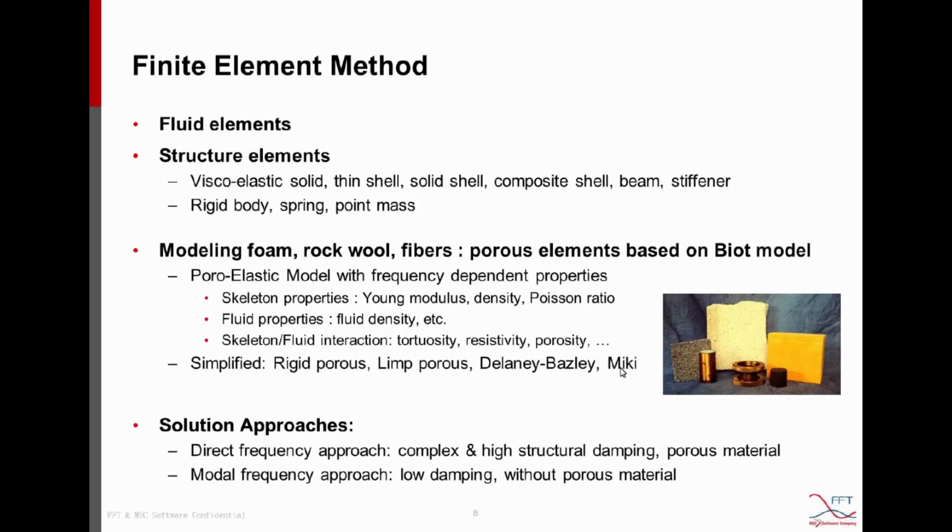So we will see the modeling of the porous material. And about the solution approaches, in Actran, we have both the direct frequency response approach and the modal frequency response approach. The direct frequency approach is very suitable for the case where we have complex and high values of structure damping and porous material. While the modal frequency approach is interesting because it often reduces the computational cost, but it's only suitable for low damping structures and without any porous material included.